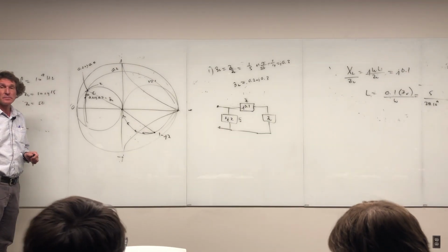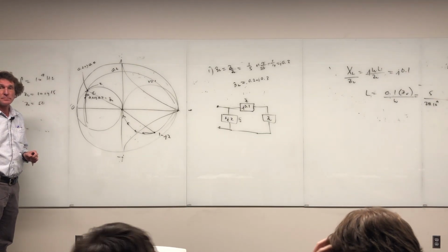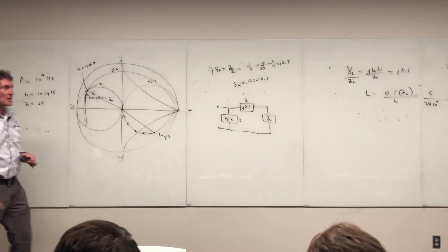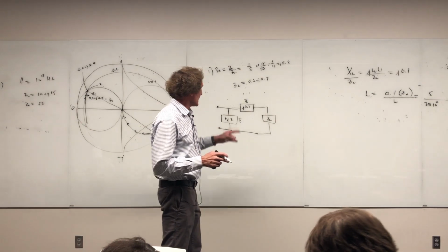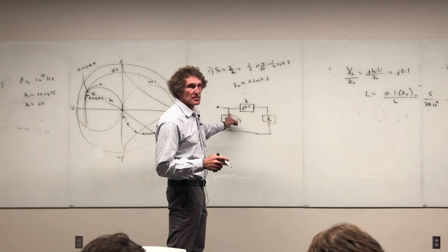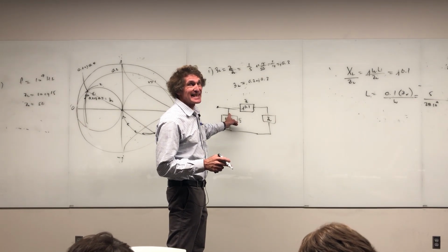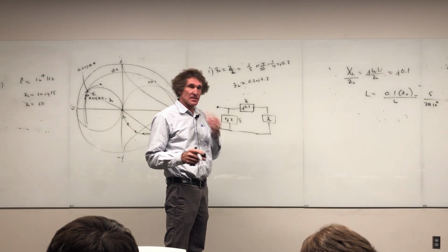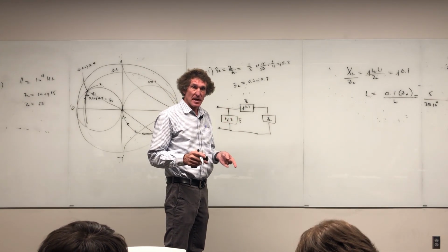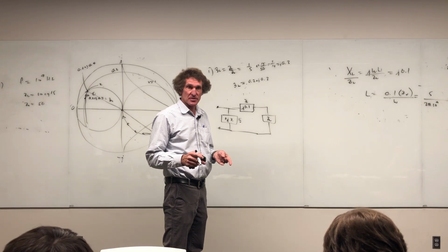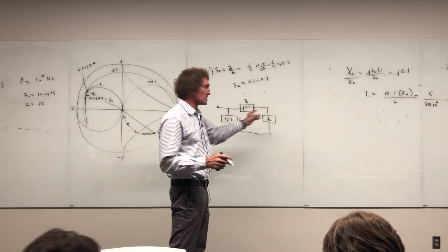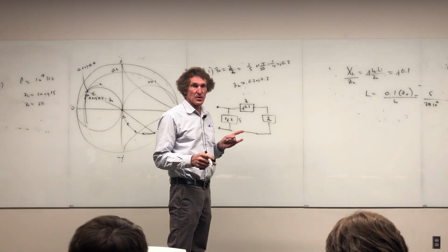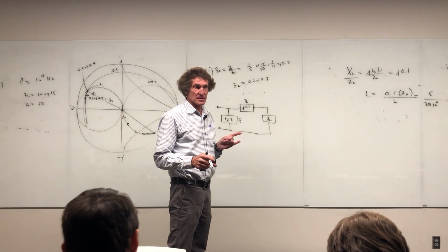Go this route. Yeah. So can you make an argument that either one of these solutions is better than the other, or are they equivalent? I'll tell you the thing people always do is this. Anything in shunt, they want a capacitor. And here's why. If it is an inductor and there's a DC offset, like to the gate of a transistor or something like this, then an inductor, like a short circuit, will just short it out for DC. That's why all your parallel elements, almost always, you want as capacitors.